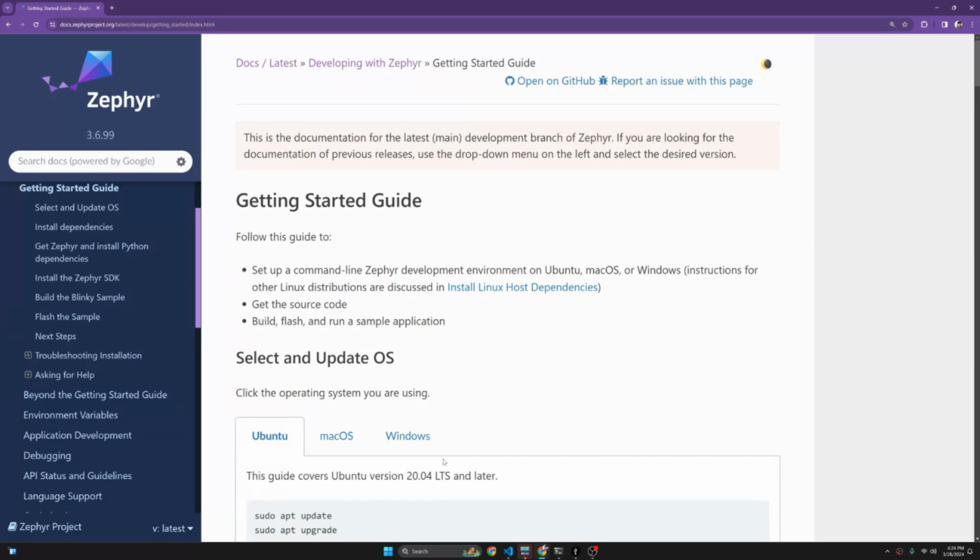And if you go through all the setup instructions, you will end up installing what we call the Zephyr SDK, which already provisions pretty much once and for all the toolchains like the ARM GCC and Xtensa GCC for ESP32, and all those tools for being able to actually build code.